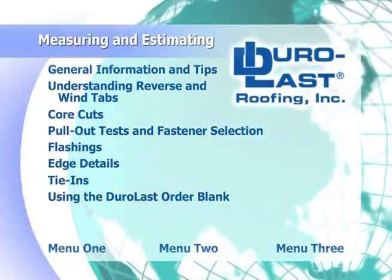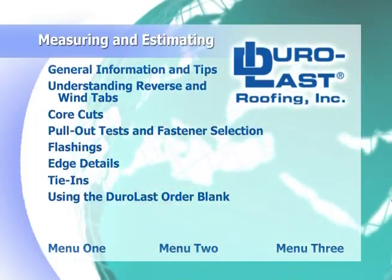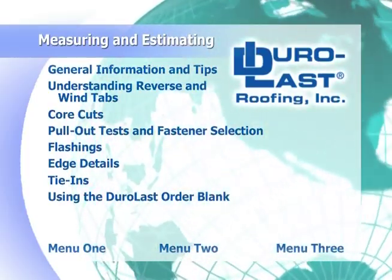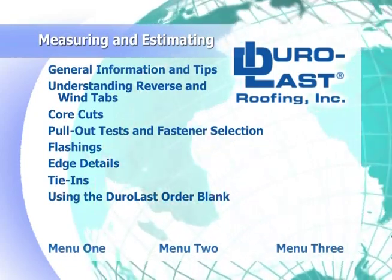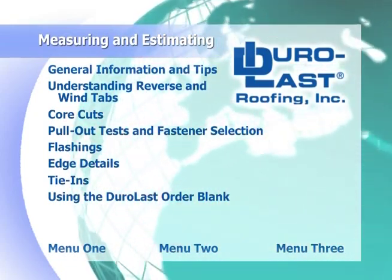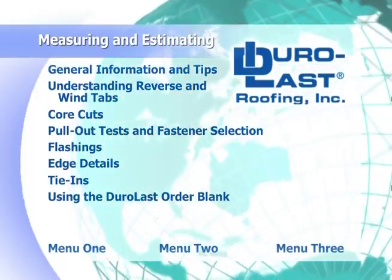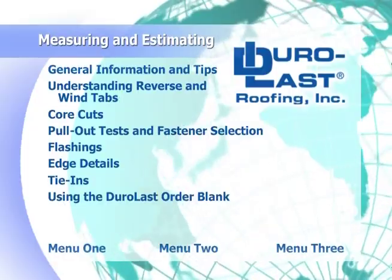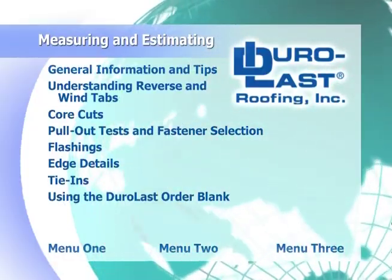First, install the roof deck sheet and fasten it every 4 or 5 feet along the wall to hold the membrane in place until you install the parapet wall flashing. Lay the parapet flashing along the base of the parapet wall with the fastening tab on the bottom side of the flashing. Make sure the factory weld is tight in the corner of the wall and deck as shown.